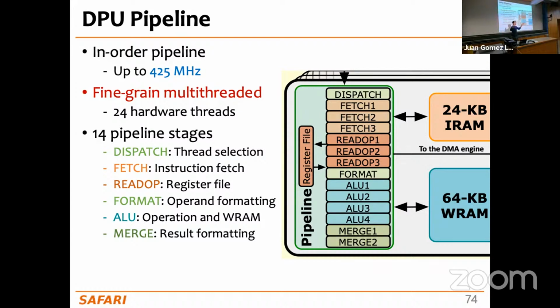They use entire SIMD units, typically called warps in GPU architectures. But every single cycle, the GPU core starts executing one instruction from a different warp, or from a different thread in this case. So yeah, that's more or less what it is.